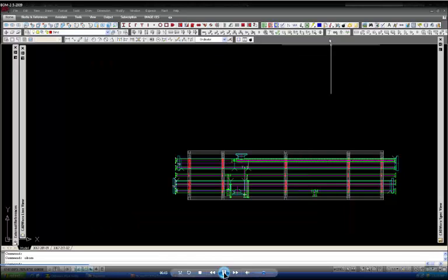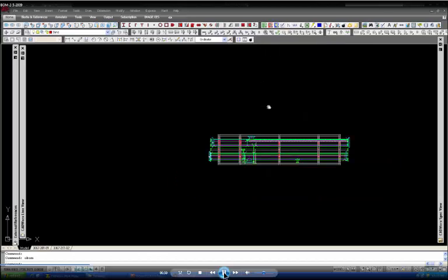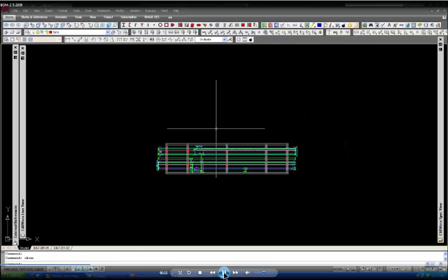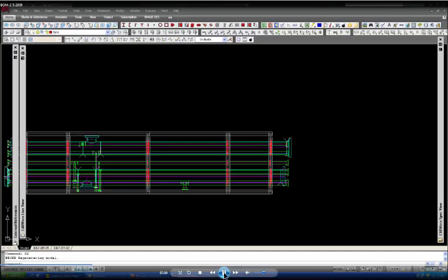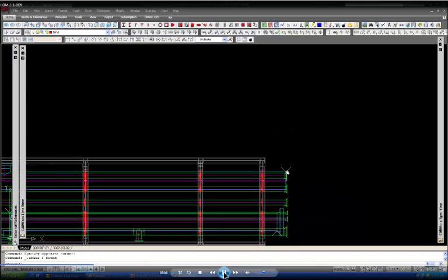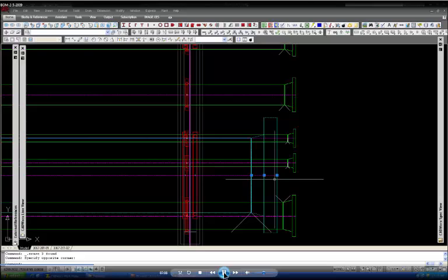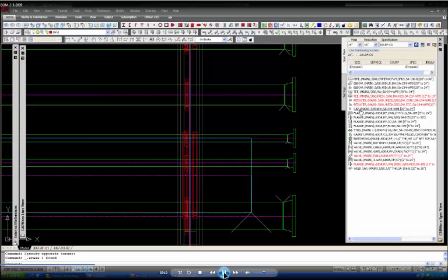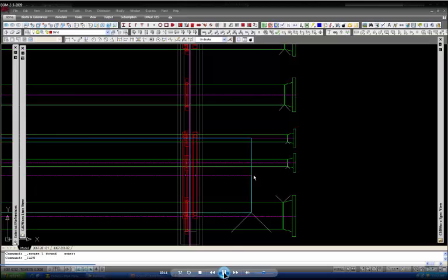And we're going to go ahead and do some editing to this CAD drawing. So first thing we're going to do is the customer comes back and they say, I don't think we're going to put another header skid out on the right end of this. So instead of those weld necks, let's just go ahead and cap that off. If we ever have to come back and add to that, we'll buy those flanges and make an extra weld at that time. So we're going to throw a couple of weld caps on the end here.